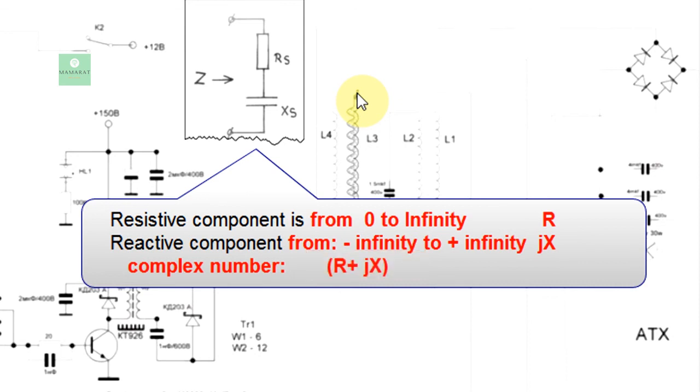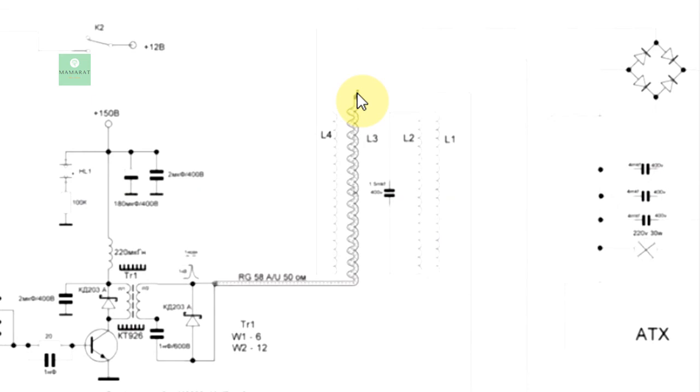And if you put the two in parallel, there's a similar formula where you do it in conductance instead of resistance. But still, once you represent it as a complex number, a real component plus a reactive component, the real component has nothing but a magnitude above 0. Although, wait a minute now, you could have a negative resistance. There is something, you can create a negative resistance electronically.